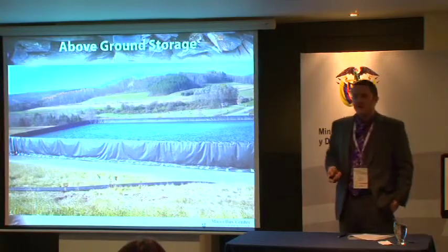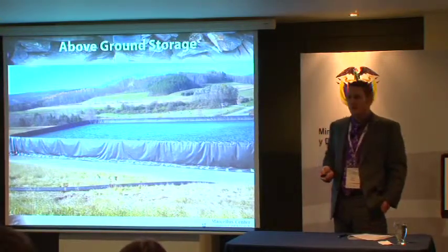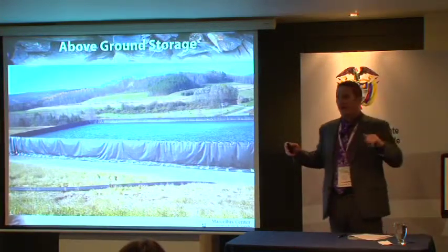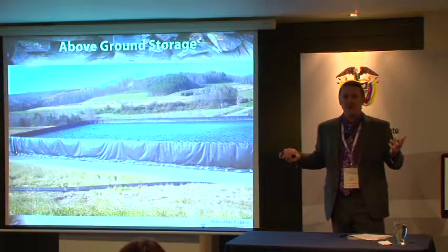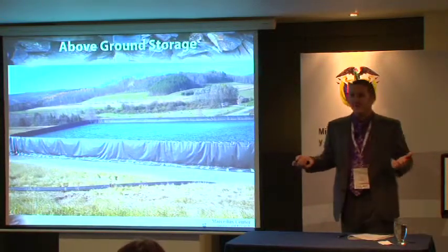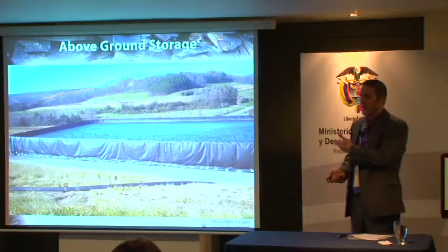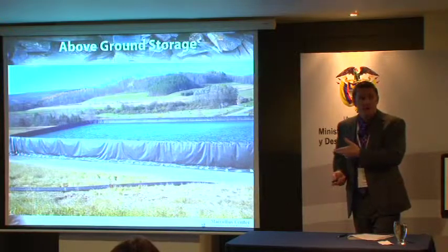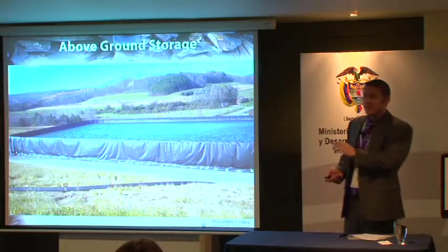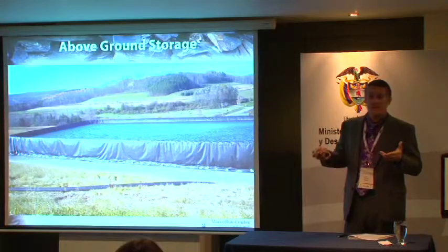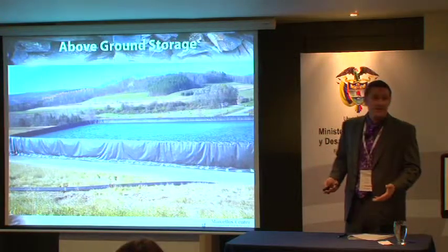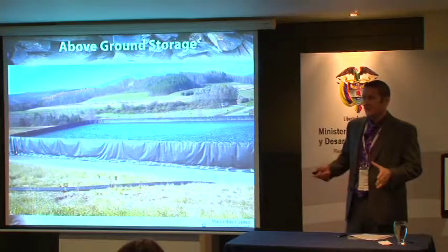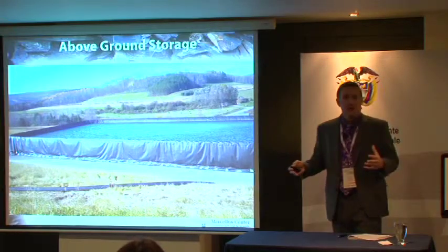We're also seeing some more innovative above-ground storage being used out there. This would be what we would call a porta-dam. It pretty much is like a large above-ground swimming pool. To think about it like that, you could store maybe 2 to, say, 5 million liters of water here. The nice thing about these is that they can be constructed in a day or two and then be taken back down. So they're mobile, they're reusable, and you don't have all the earth moving associated with an earthen impoundment.